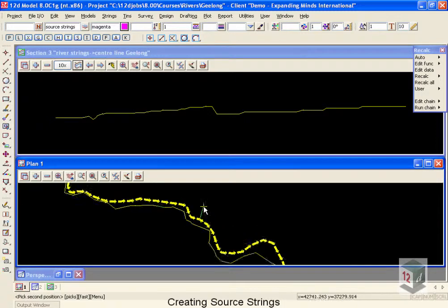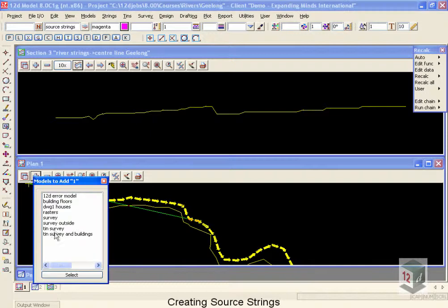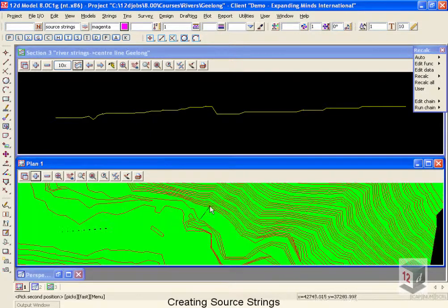Now I'm going to zoom out a little bit, and I'm going to want to add on my tin so that I can see exactly where I'm moving across my sections. Now with any of our design software packages, you don't want to define your cross sections higher than you expect your maximum flood levels. Otherwise it reduces the accuracy of the design packages. For these areas, we don't expect the water levels to ever go above an elevation 165.